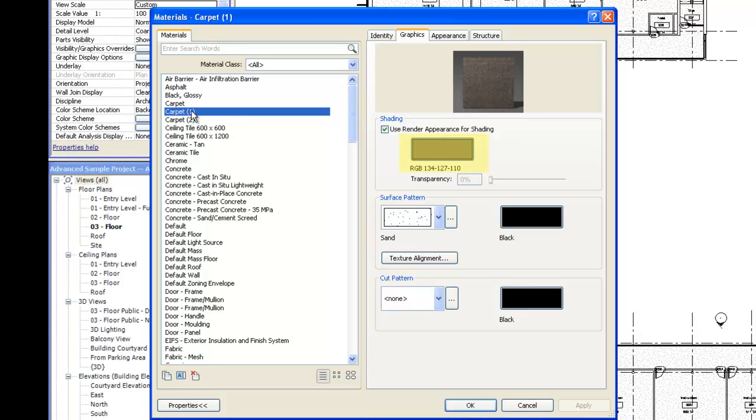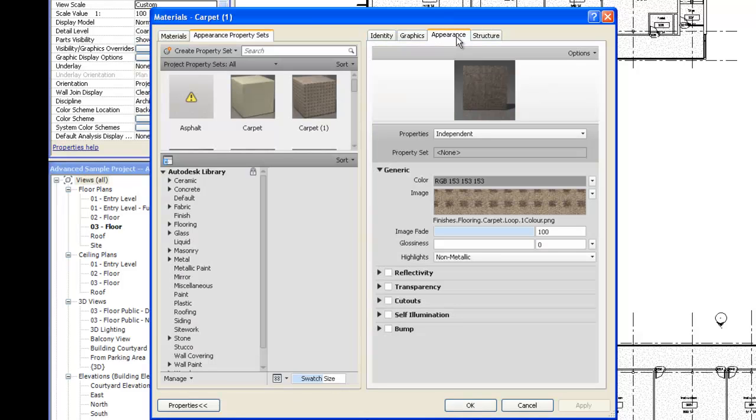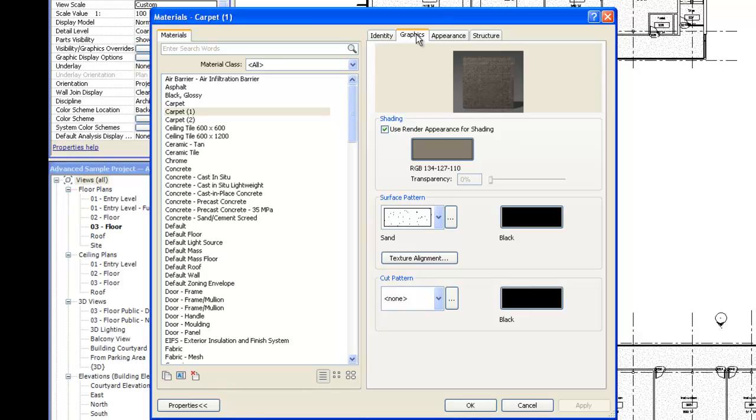We see that the material has a color as assigned in the Graphics tab. And it also has a rendered appearance, defined in the Appearance tab. Unfortunately, ElumTools has API access only to the information from the Graphics tab. This is a decent starting point if the graphics color and the transparency data are reasonable. ElumTools can calculate an equivalent reflectance from the RGB components of any color. The graphics transparency as a percentage is also easily accessible.